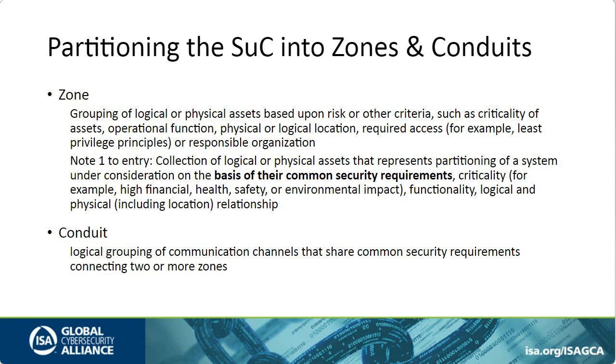It could be geographical location, or it could be the criticality of the equipment. Oftentimes, you will split apart safety systems from control systems. The key thing is that when you have a zone, you really want the security requirements for that zone to be common to everything within that zone.